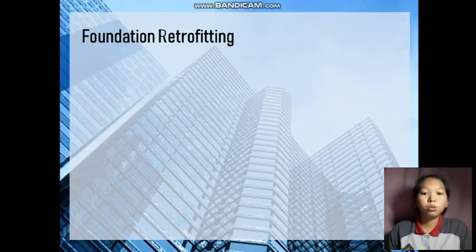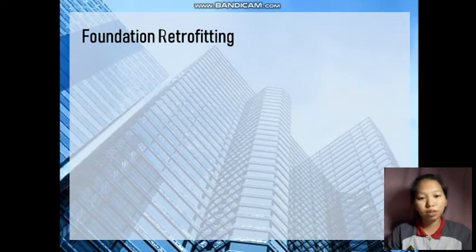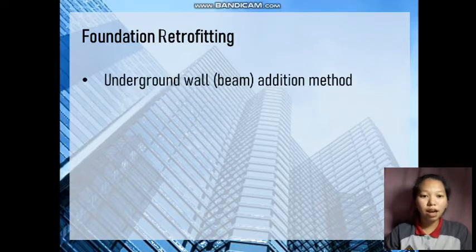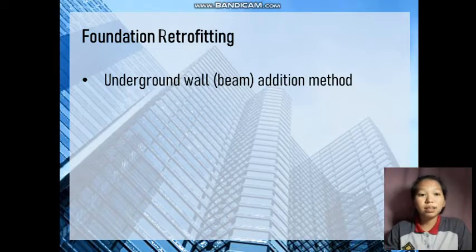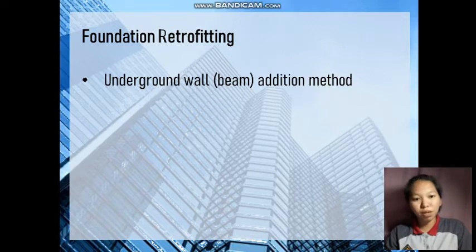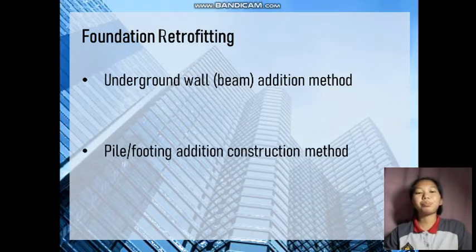So now let's go to foundation retrofitting. The first method for foundation retrofitting is the underground wall or beam addition method. It is connecting the foundation with cast inside diaphragm walls and underground connecting beams to distribute stress and ensure the stability of the entire system.